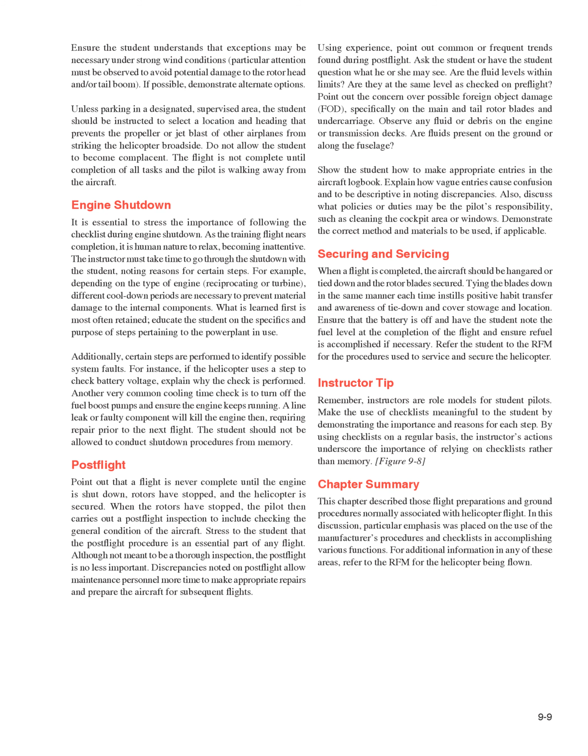Unless parking in a designated, supervised area, the student should be instructed to select a location and heading that prevents the propeller or jet blast of other airplanes from striking the helicopter broadside. Do not allow the student to become complacent. The flight is not complete until completion of all tasks and the pilot is walking away from the aircraft.